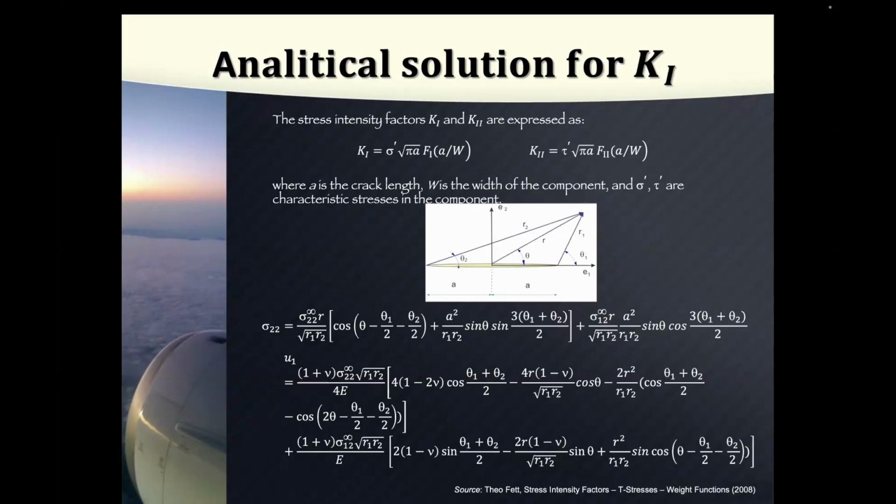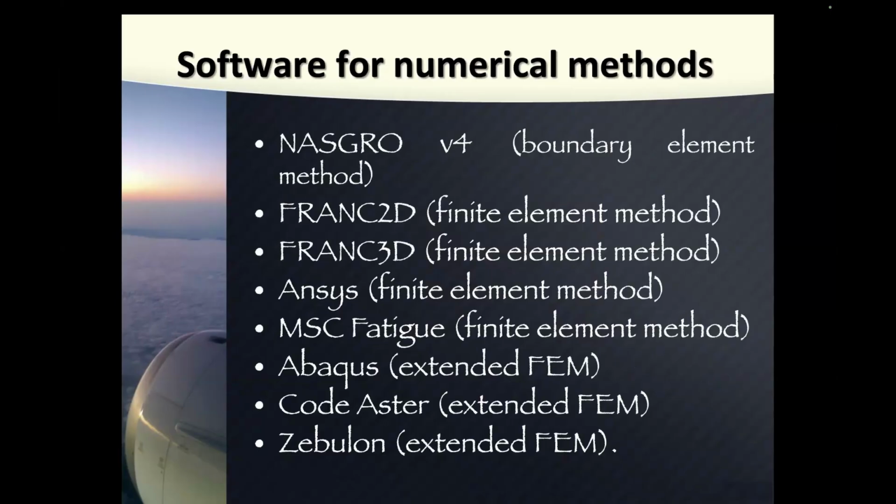If you have a structure which is complex, with complex geometry, this formula is more or less useless, because it can be applied only when you have a crack in the middle of the plate. So this is why numerical methods are very important nowadays, because using some of this software, we can evaluate the crack growth and the number of cycles that will lead to the final damage. And I have used them all in the last 30 years.